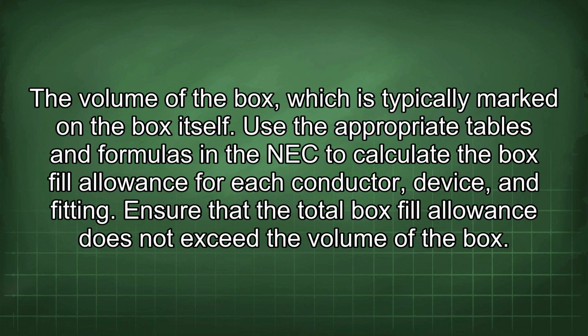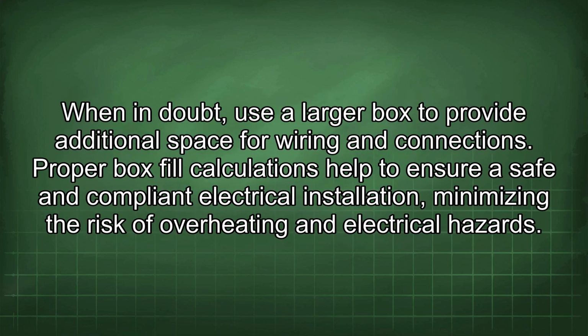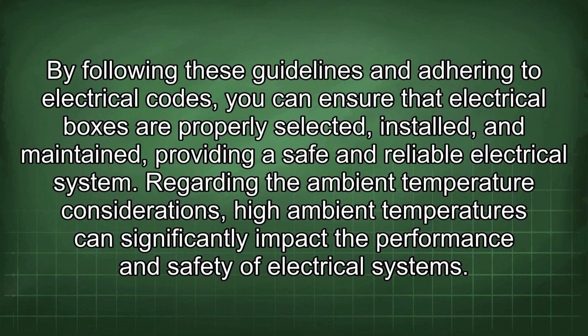Use the appropriate tables and formulas in the NEC to calculate the box fill allowance for each conductor, device, and fitting. Ensure that the total box fill allowance does not exceed the volume of the box. When in doubt, use a larger box to provide additional space for wiring and connections. Proper box fill calculations help to ensure a safe and compliant electrical installation, minimizing the risk of overheating and electrical hazards. By following these guidelines and adhering to electrical codes, you can ensure that electrical boxes are properly selected, installed, and maintained, providing a safe and reliable electrical system.